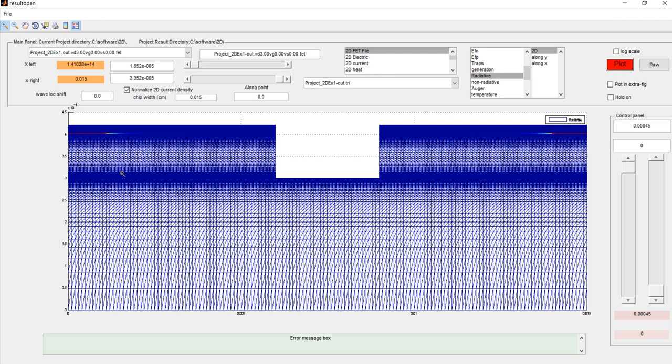Of course, because we don't put ITO. We only put P-GaN, so you see a very strong crowding. Right now there are two solutions. One is to put ITO. The second is what they call flip chip. In a flip chip, the whole top layer is the P-type contact, and then we spread the current through the N-type. So we make the N-type as conductive as possible, make N-type like ITO, to make the current vertically injected.